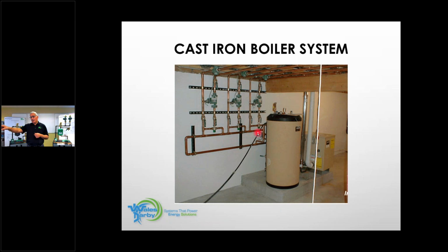You want to make sure you get your highest water temperature first, because we're going to start blending it down even before we come out of the mix. Something to pay attention to when you're laying out systems like this. It is a cast iron boiler, and if it was just a plain Jane cast iron boiler, you do also have the ability to add outdoor reset to that boiler if it's a young boiler and make it even better.